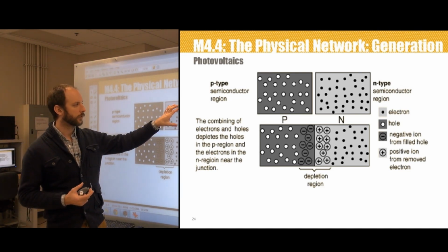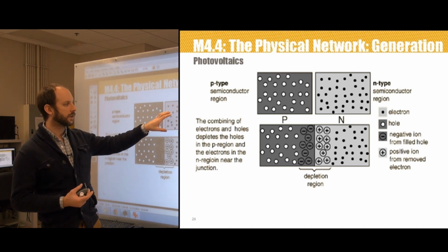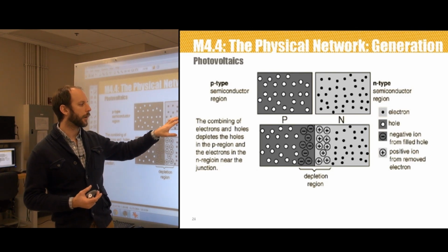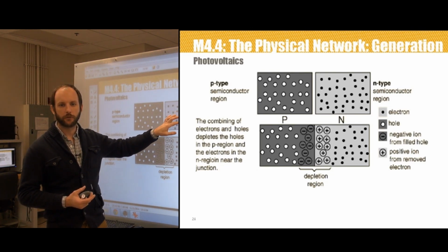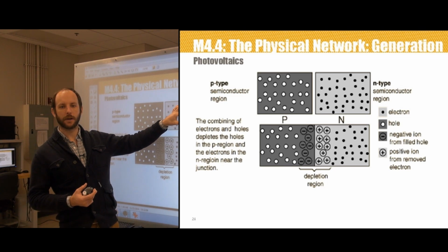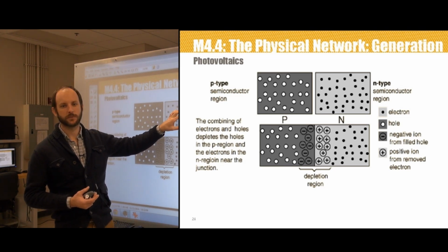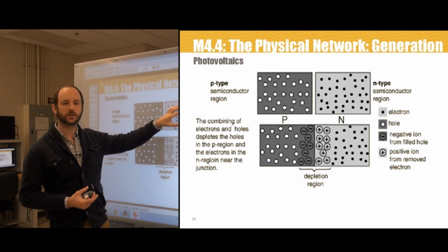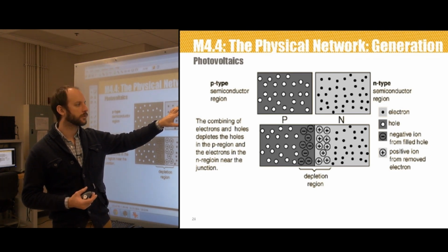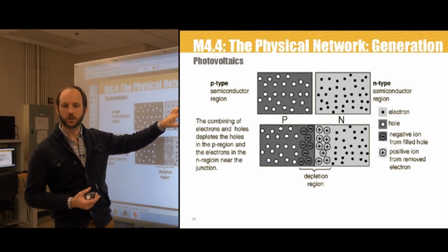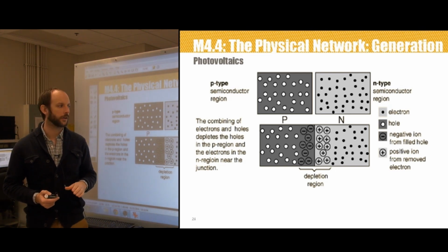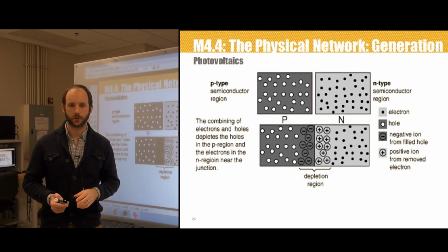electrons. So we're showing we've got some sort of N-type semiconductor. It's silicon. It's had phosphorus injected into it. What this results in is a bunch of electrons that are free to move around. They're not bound to any atoms inside the structure of the silicon anymore, and therefore these electrons are easily moved under the influence of voltage. They're not held by the nuclei of the atoms from which they originated. These free electrons are typically called N-type charge carriers because they have a negative charge.